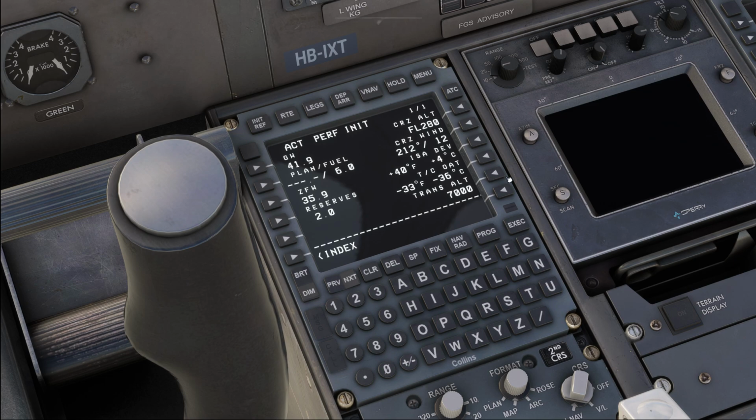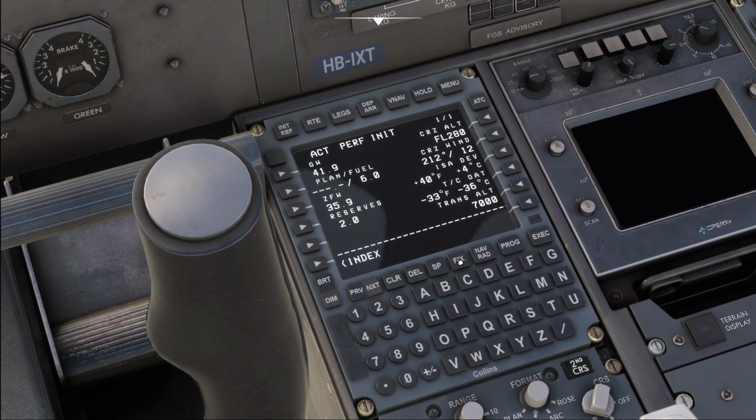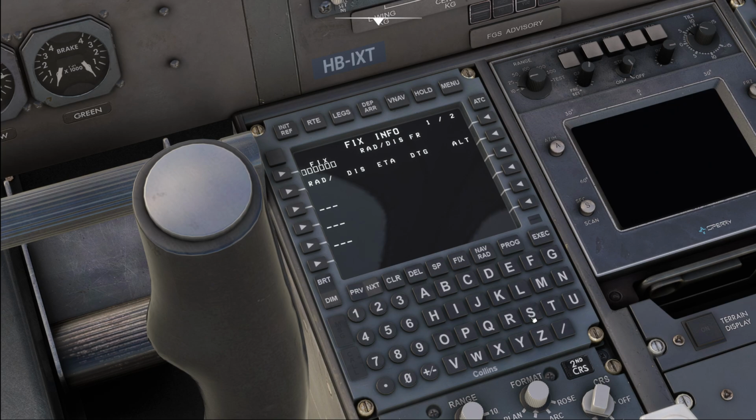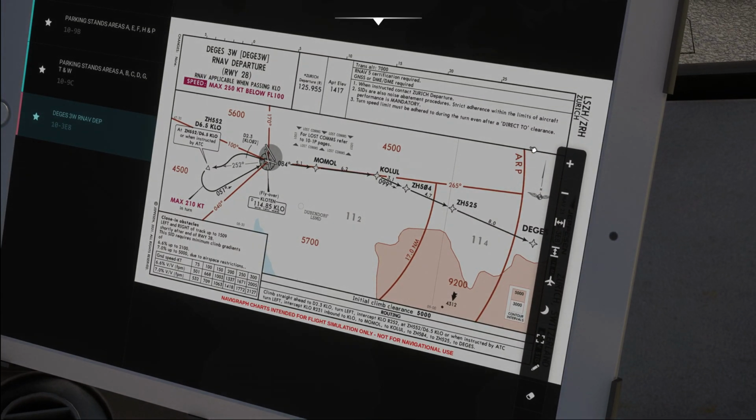However, there is a little bit of optional data that you can enter as well, starting on the fix page. Over here it is good practice to enter your departure airport and draw a 25-mile ring. You do that by hitting /25 and then include it down here on the radial distance line, and this now draws a 25-mile ring around our airport. This is good practice because the MSAs given on charts are always within 25 miles around the fix in question. So today we've got the airport as fix, and then 25 miles is our MSA down here.